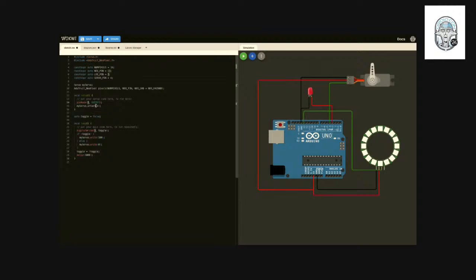And then we can replace these magic numbers in the code with these constants. And the benefit of doing it this way is, it's easier to assign if you're moving to a different board. Now you just have to change these numbers here, and everything should work. We want to move the LED pin here.